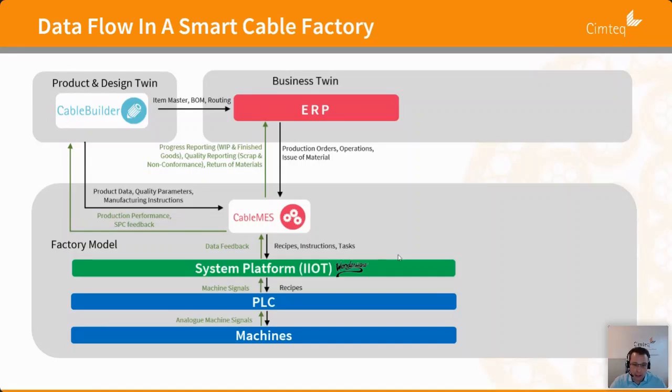So really what you see here, you've got this IoT solution, the SCADA solution that many companies already have, and that SCADA solution is collecting data from the machines, from the sensors, whatever you have, and it's super powerful. It can store huge amounts of data, and it stores it in a tool called Historian, which is a huge database. So you can store diameter values by the second, or temperature or pressure values by the second or millisecond. There's no limit to it.